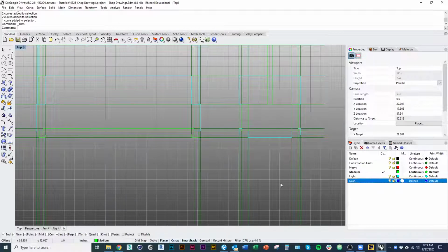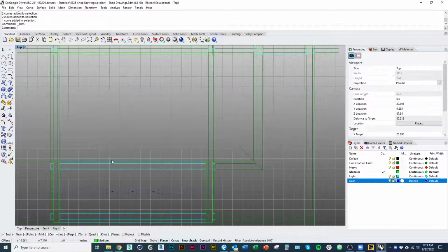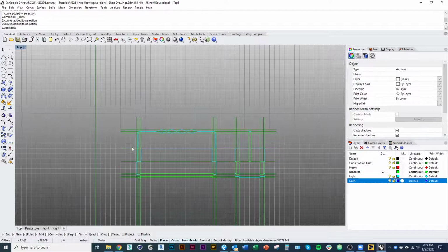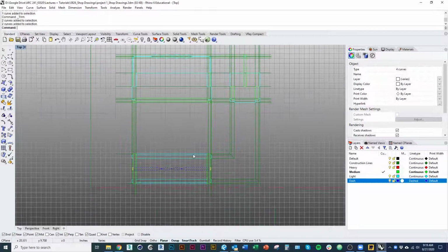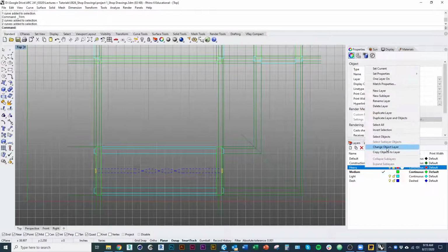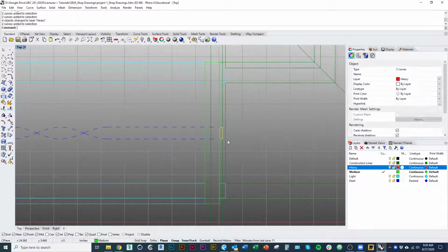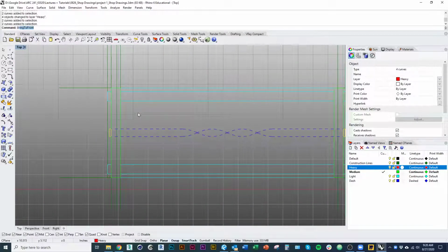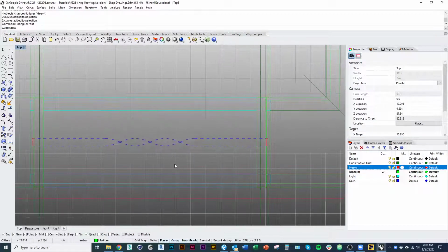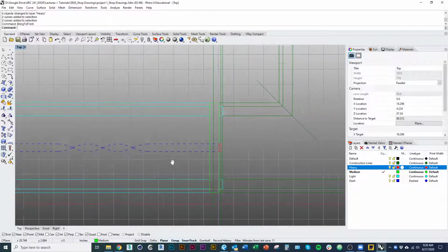But I haven't used my heaviest line weight yet, because I haven't cut through anything. So just like I'm about to do with my sections, this little handle here that I'm actually cutting through on my plan to show the toolbox below the handle, I'm going to put that onto my heavy line weight. Because I always want the section cut to be the heaviest line weight. So anytime we're cutting through an object, it's the closest to the picture plane, and so we want it to show up as the thickest line, the heaviest line weight.